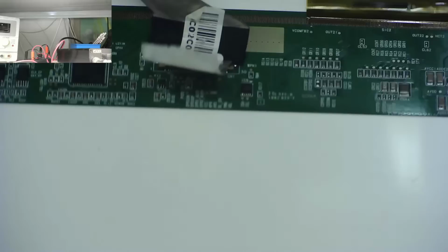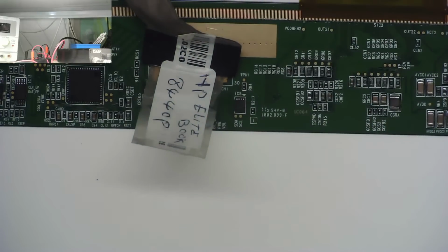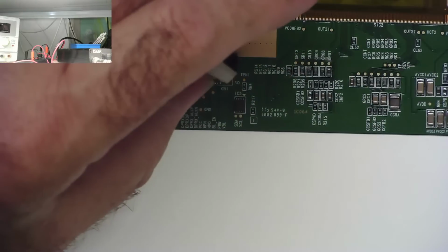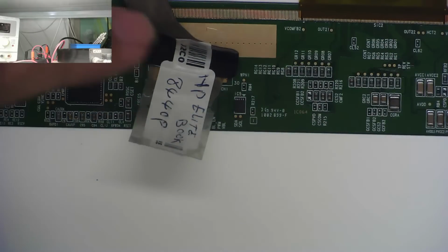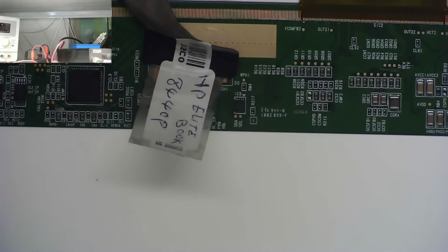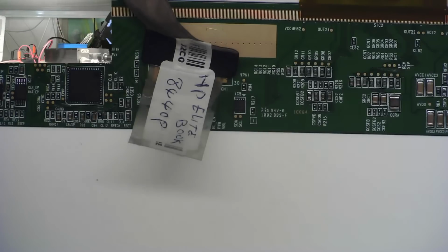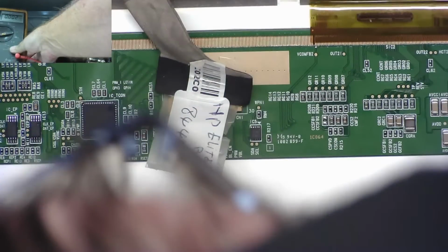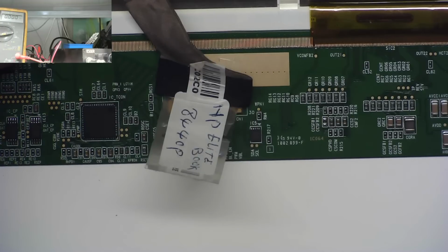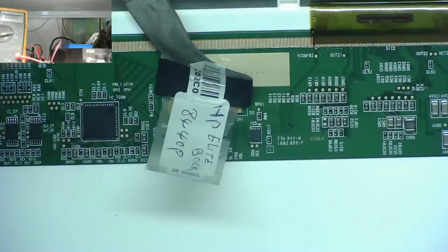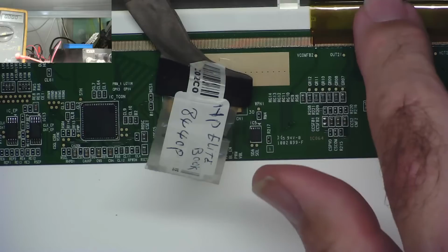But this one has a blank screen with no image, just a backlight. The other one gives a picture. But I can't see any difference on this with the multimeter. Certainly I can't see anything there to say there's a difference between the two boards. So I think we have to assume that all the voltages are present, which is a good thing, but it doesn't really help us to find the fault. So I think next we have to have a look at the data sheets. I'm just checking if these things are warm, by the way.